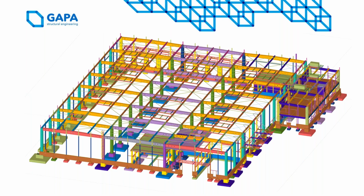Now, if we focus a bit more on the precast design aspects, we have used prestress on this project for the design of the primary precast beams, the precast purlins, the mezzanine double T elements, so pretty much all precast elements apart from the columns and the column sockets.